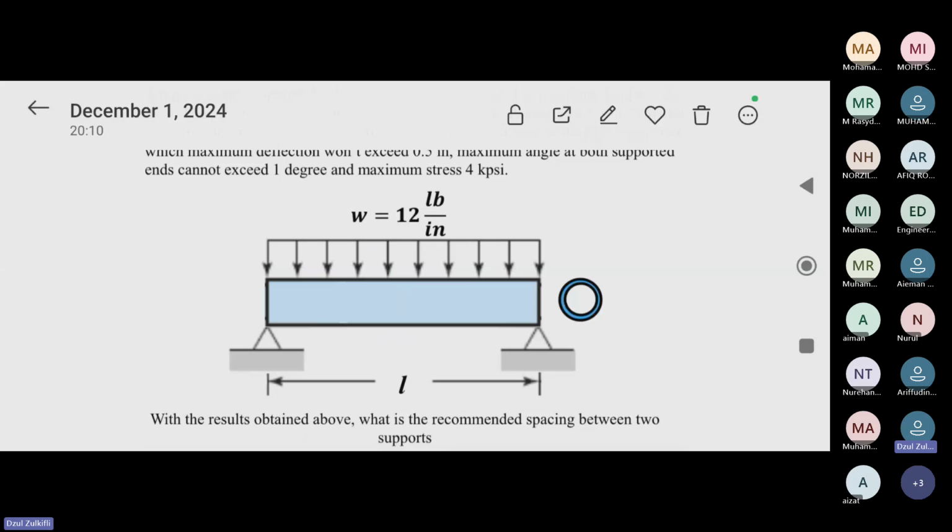What I want to share mainly here is that API 574 is not necessarily the end of the road, but API 574 thickness is quite low already, such that if you want to be careful, if you can repair, you repair it, right? Not even think about FFS actually. If you can repair, just repair it. But if you really cannot repair it, then you can do detailed engineering calculation first. If the detailed calculation shows a value that you cannot meet, then only you do FFS. Okay?